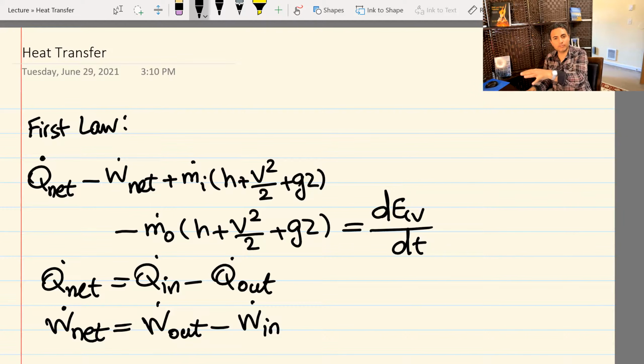And if you put it in this form of the first law of thermodynamics, which you can memorize easily, then it makes more sense. There's one catch to this, and I don't know if we're going to deal with that in this course, but there's one case where W dot out is waste and it still is W dot out, and that's friction.